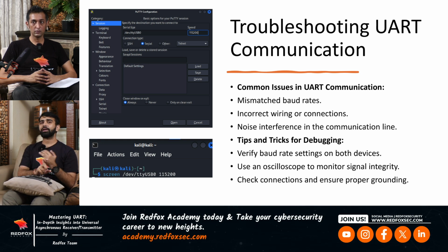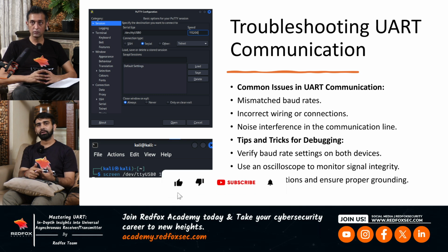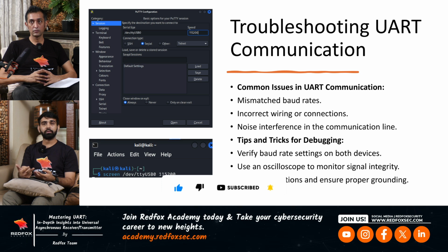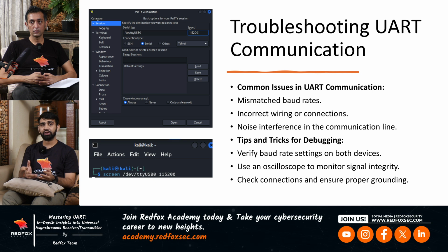And if the baud rate is correct but we still do not see the data in the serial communication, there will be an issue of wiring. When connecting RX and TX, sometimes the vendor removes the tags of the pins. RX, TX, GND, VCC and multiple test pins are there. We analyze from that, and if we wire the wrong test pins, there will be a problem, so we need to detect the test pins correctly.